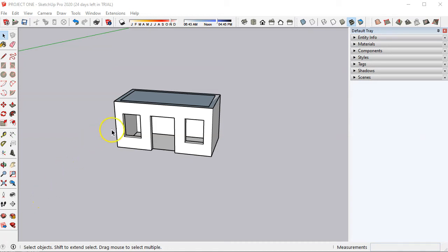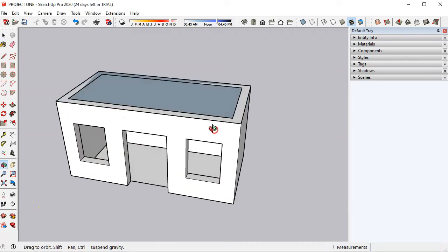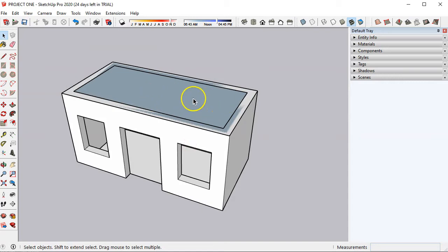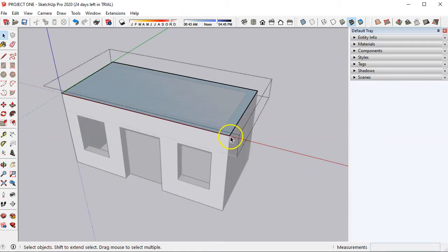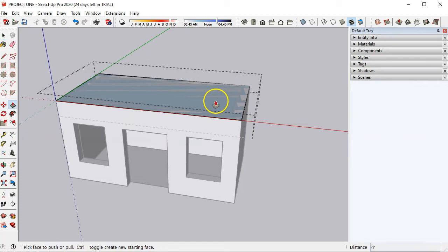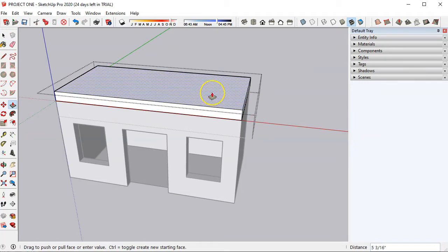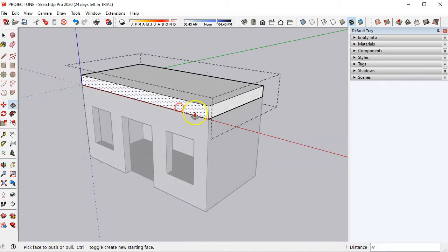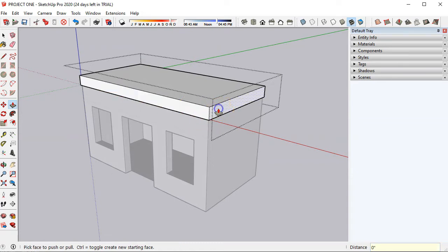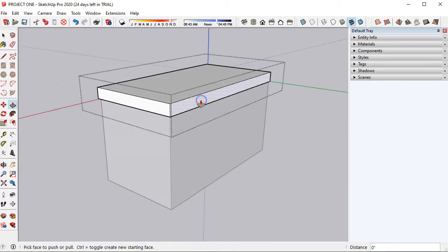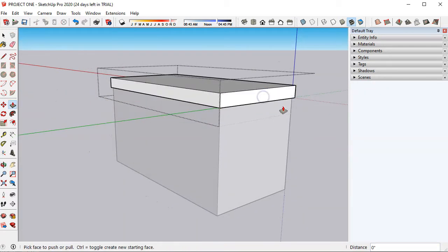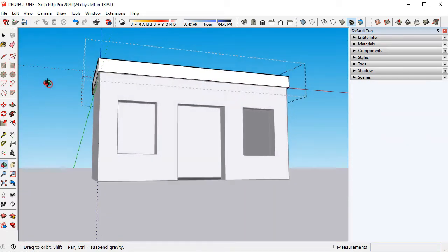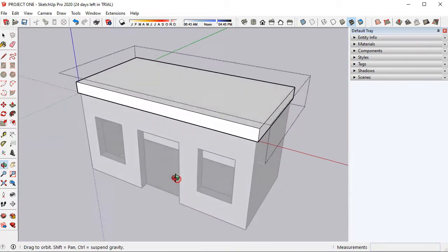For the parapet roof, you'll start by editing the roof group here and push-pulling this surface up 6 inches, and then all around the perimeter you'll pull the sides out 1 inch. I'm going to double pick, so it's pulled out by 1 inch all the way around.